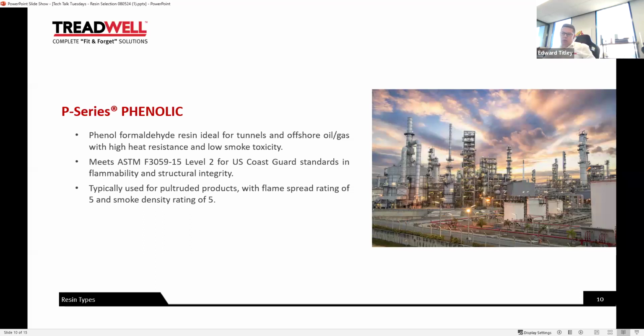I will just say, and this might preempt some questions that come up, the other aspect of resin selection is cost. Now, if no spec is given, as we know, lowest common denominator becomes cost, and therefore, especially in a chemical environment, we might get a product that's not fit for purpose, that's going to give us a non-optimum design life. So hence we'd say specify resin to get the performance you want.